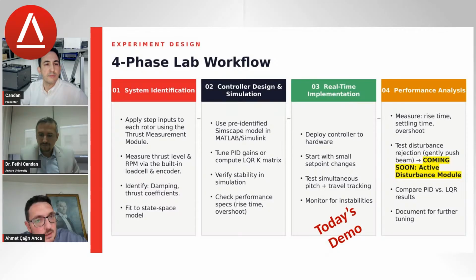The second step is control design and simulation. Use the pre-identified SimScape model in MATLAB and Simulink, and tune a PID or LQR or any other controller method.